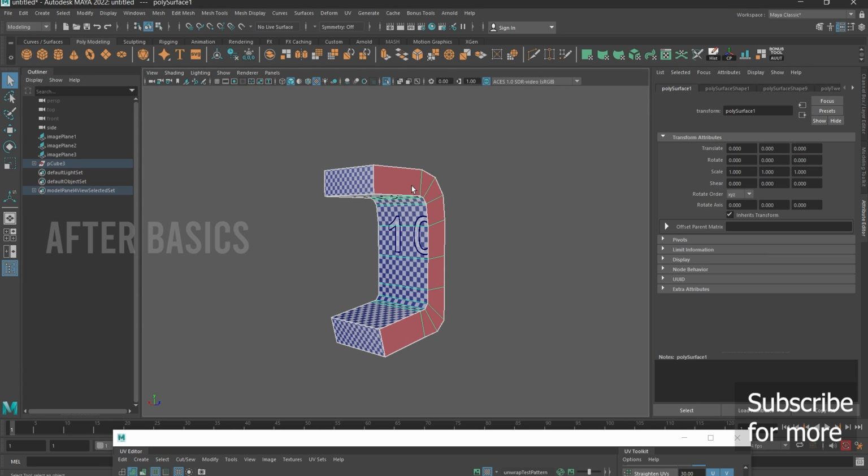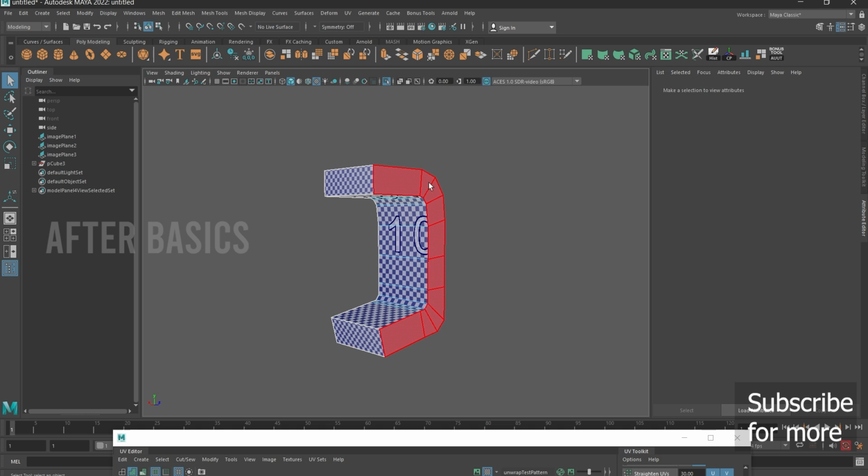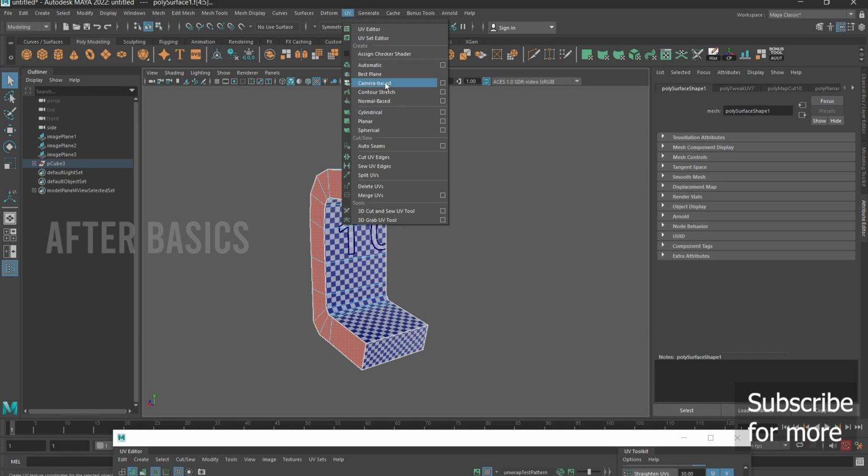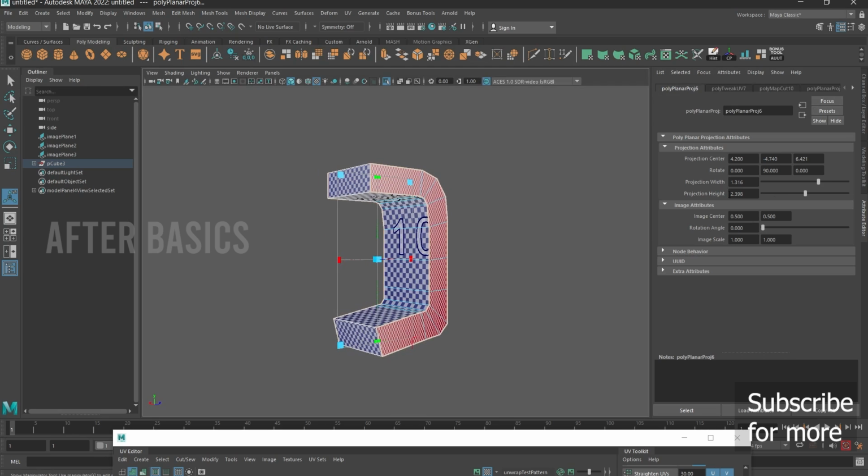So done. Then I'm gonna press this UV shell, use this UV shell and use planar on it and put 5. Okay, 5 is enough. The same value is the important thing. Put the same value. So whether it can be 3.117 here and here. Okay, make sure it is the same.